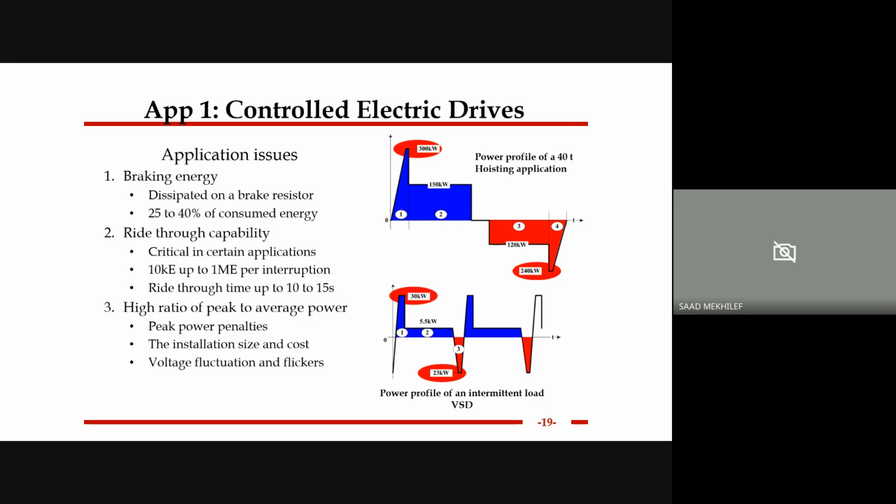In the microgrid system, at the start you have a very high power demand, and then it goes back, because the rating here is around 150 kilowatts. But at the beginning there is a very high rush current to start, because it is moving from static to dynamic, and then it goes to the rated power. During this peak there are two options: either we over-design the systems to cater for this, or we provide a storage which can be used.